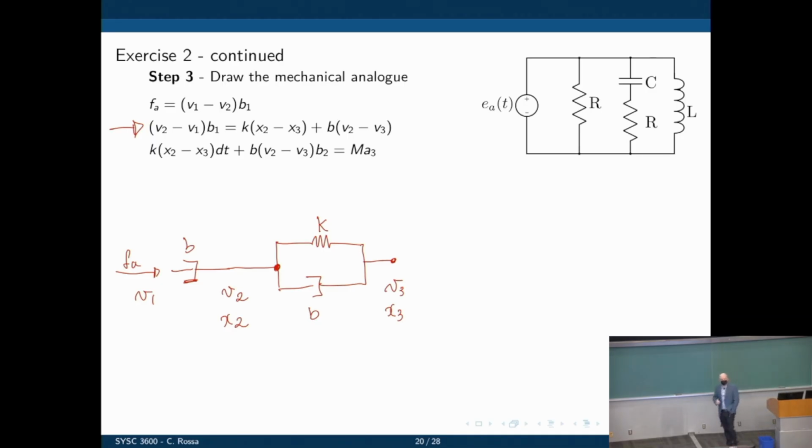And now that we created a third node, we can go to the last equation, and you see that on the one side of the node, we have the spring and the damper, exactly as we just modeled there. Right, that's already taken care of, and that is equal to the acceleration of the mass. So we can simply multiply this or attach the mass here, M, and in this point, we have A3 as well. That is the equivalent system there.